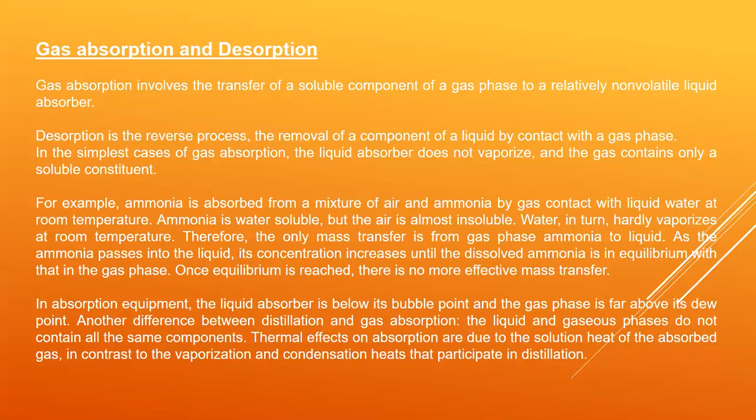But in the case of distillation, since your vapor is being produced from your liquid feed, your liquid and your vapor phases have the same components, but not necessarily the same composition. Now, thermal effects on absorption are due to the solution heat of the absorbed gas, in contrast to the vaporization and condensation heats that participate in the case of distillation.